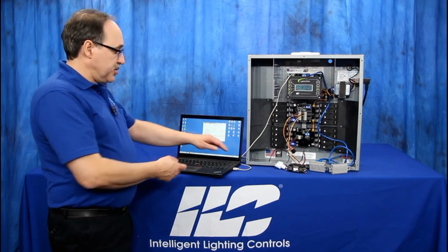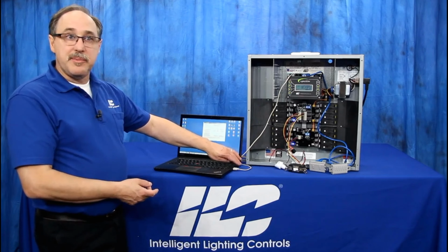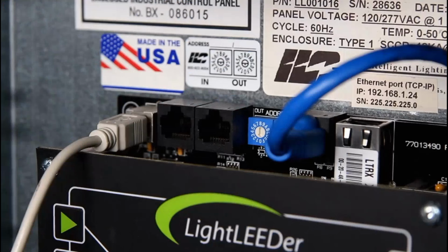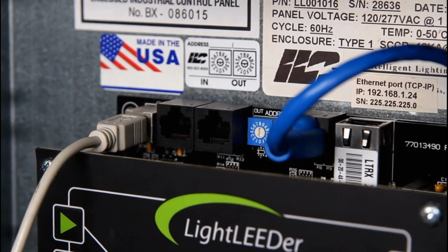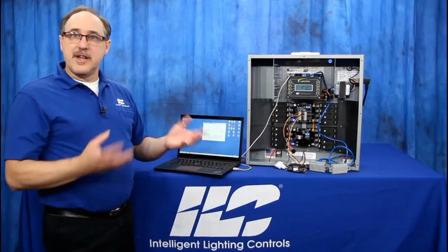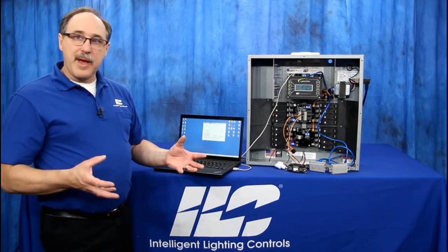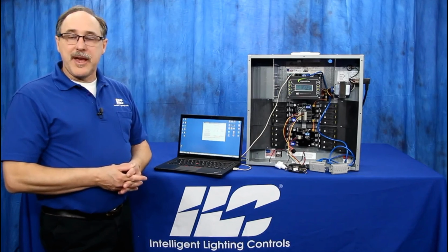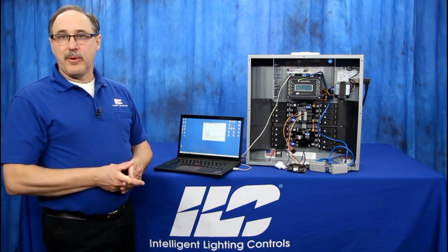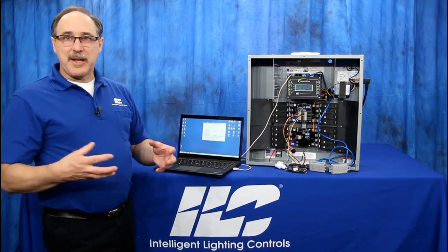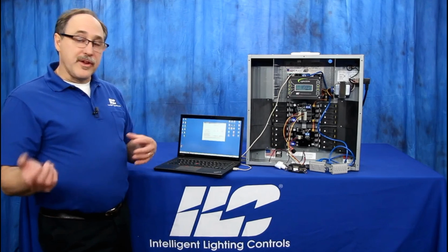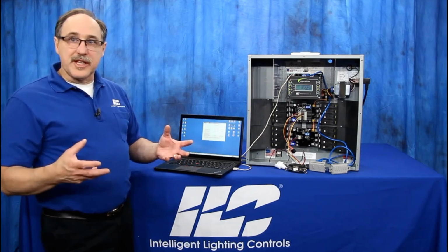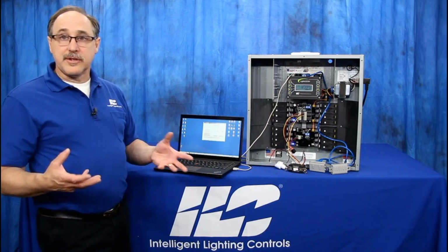You can also do the same type of operation using a TCP/IP port, and you can go to the TCP/IP port on your panel if the panel has one. A lot of standalone panels don't have an IP port unless it's requested for the job type. If you have a network of systems or a network panel, typically the master panel in a network will have a TCP/IP port, because on larger systems like that, it's expected that the customer is going to load this software on their computer system, and they're going to connect to it and make timer changes and things like that after you're gone and you're done with the job.